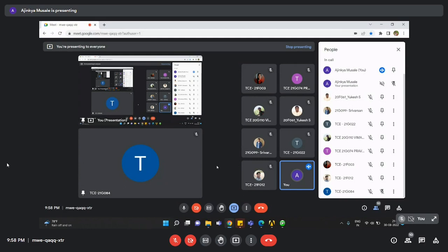In today's session, we have imported the external 3D geometry and we have meshed it. So that was the basic difference between the first session and this session. In the first session, we dealt with a 1D element, like one dimension element, that was line or beam. And today we dealt with a 3-dimensional element. We have seen today the total deformation, that too in 3 directions, right?